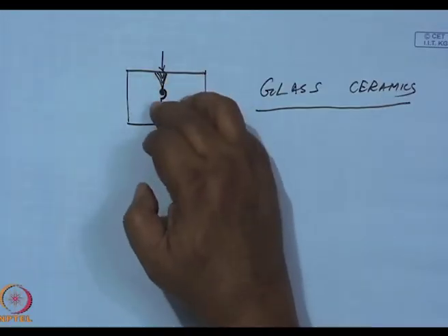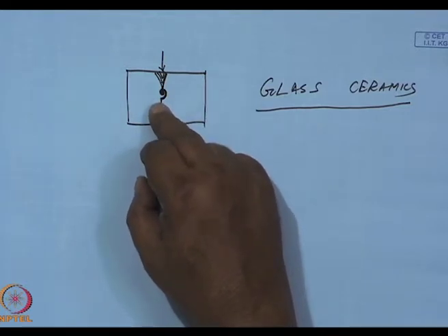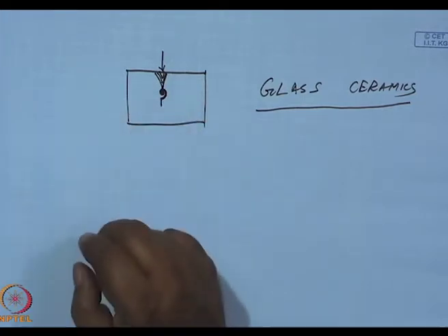Now, if you saw there a huge number of ceramized glass in the glass matrix. Now, if the amount of the ceramized glass in the glass matrix was small, crack propagation would have been easier, the material would have a smaller load bearing strength. But as the number of impediments increase, the more the number of this crack deflection, and hence the strength of the material increases.